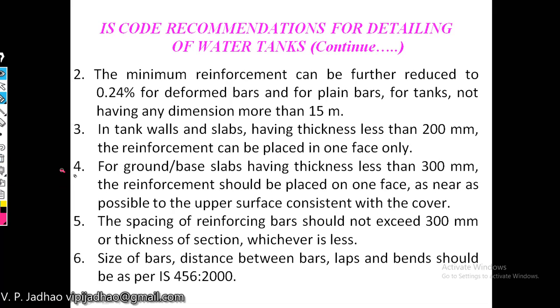Then for ground or base slab having thickness less than 300 mm, the reinforcement can be placed on one face as near as possible to the upper surface consistent with the cover. The fifth recommendation is spacing of reinforcement bar. It should not exceed 300 mm or the thickness of your section, whichever is less.